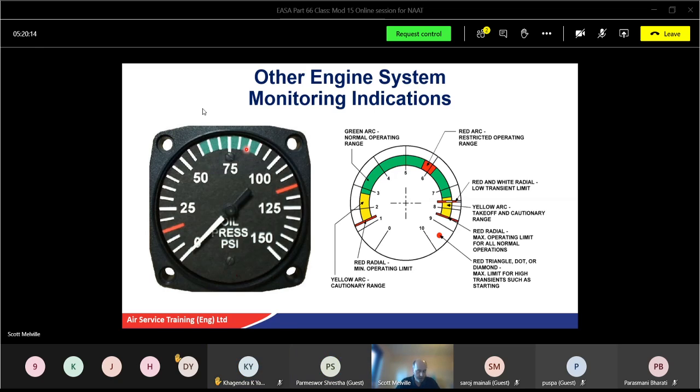Okay, good. Again, the direct pressure indicator is only effective up to a certain forward speed of generally around how many knots? 50 knots. 50 knots, yeah. And what do they not compensate for? RAM effect. RAM effect, good.